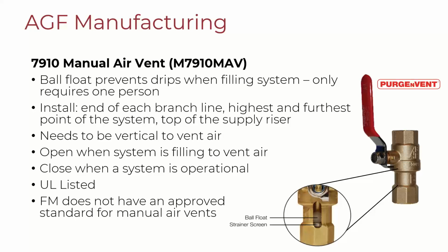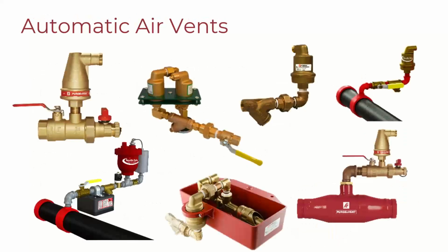It is still a manual valve. You can still rotate it from on and off to release any trapped air, but you'll stop it from flowing water out like a fountain once the water comes up to it. So it's kind of a semi-automatic manual air vent. And there are a handful of manufacturers who are making automatic air vents.